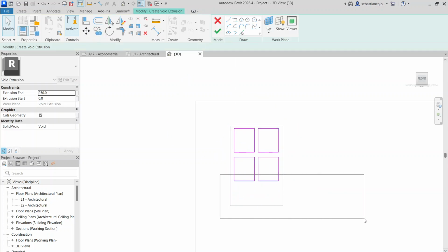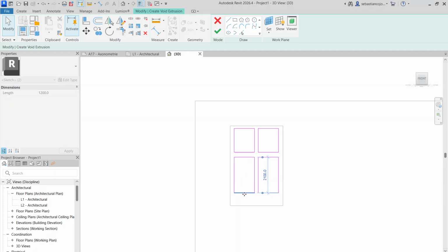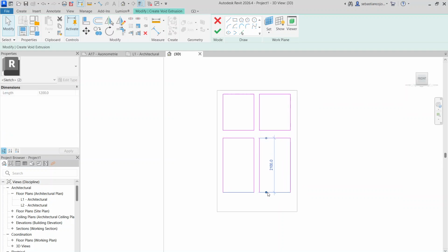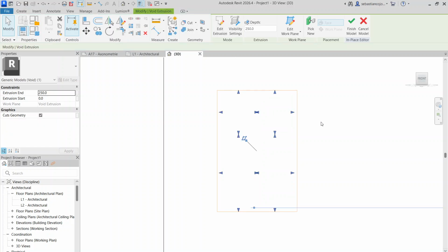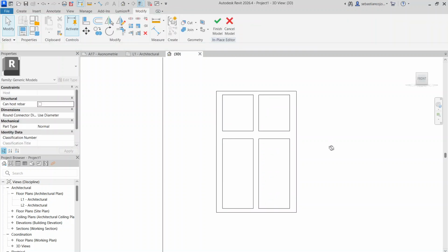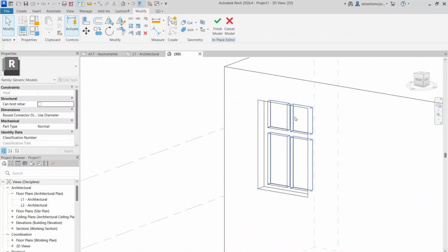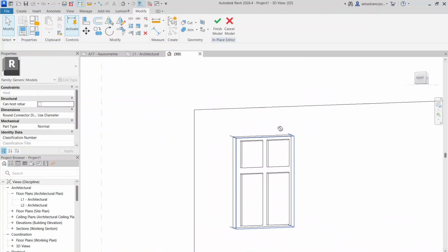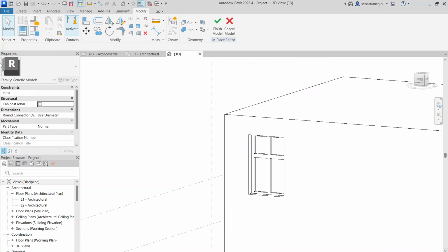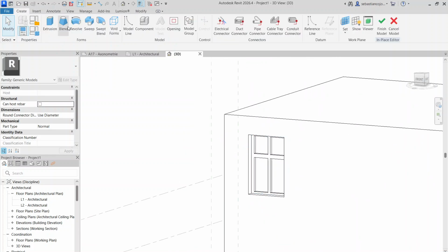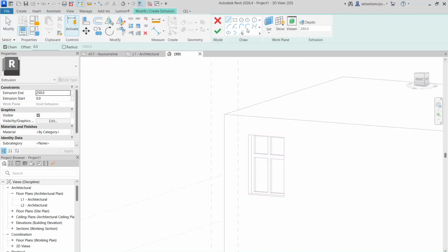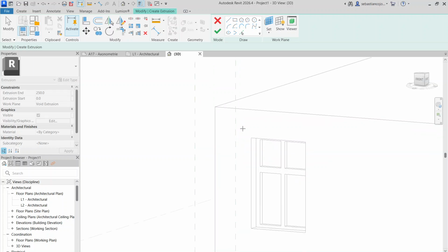yellowish orangish volumes. Now what is interesting, that you can use the controls and you can select 2 sides at a time, and you can drag it downwards. I can click like this on the green tick, and now you can see that I have a window, which is pretty neat. And also you can create yet again an extrusion. This is one of the most useful tools for generic models. Extrusions are the safest from a geometric point of view.